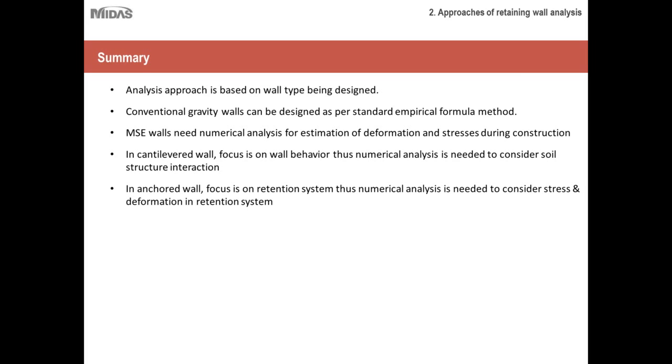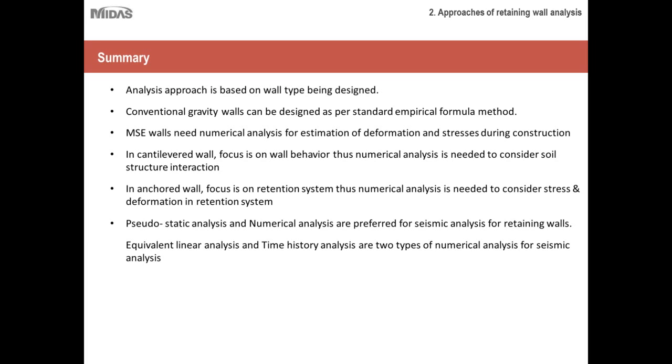And in anchored walls, the focus is on the retention system, and thus numerical analysis is needed to consider stress and deformation in the retention system. Pseudostatic analysis and numerical analysis are preferred for seismic analysis of retaining walls. Equivalent linear analysis and time history analysis are two types of numerical analysis for seismic analysis.